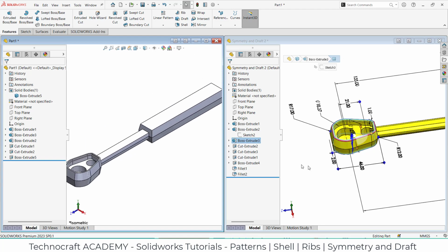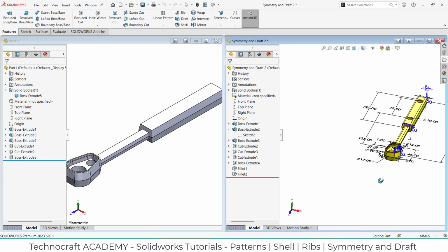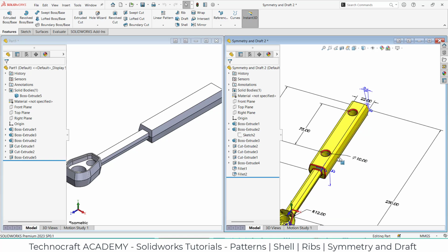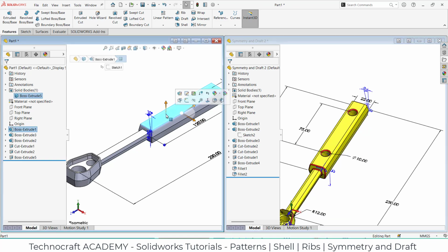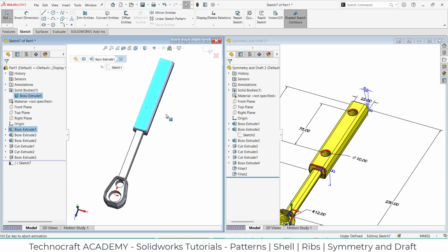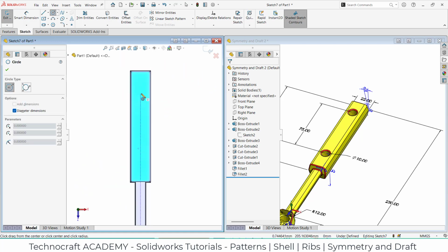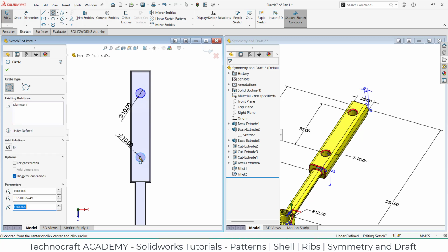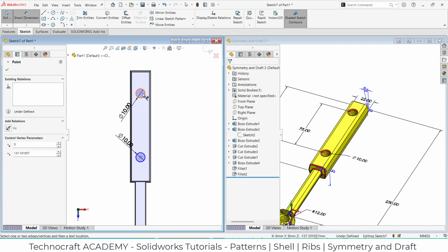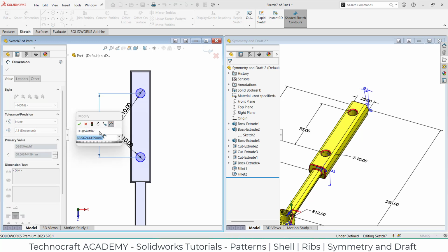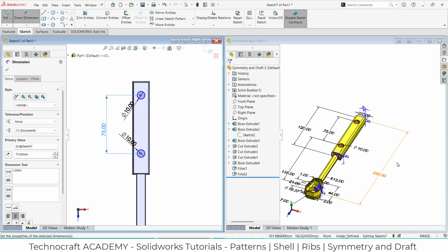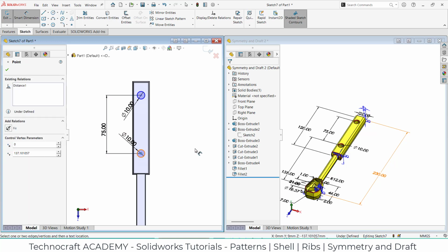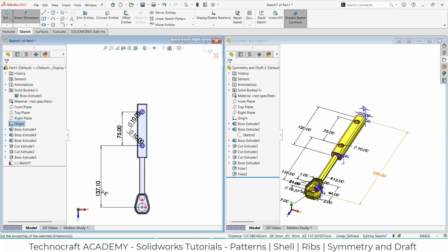So we are at the final stage of this one. So this cavity we can easily create it. 75, just select this face, sketch on it, make it normal, use C for circle, one circle here, diameter 10 you can mention. Here is also one, diameter 10 you can mention directly. And between these two distance also I should specify. From here to here it is exactly 75, and he has given from this origin point to this point is 135.